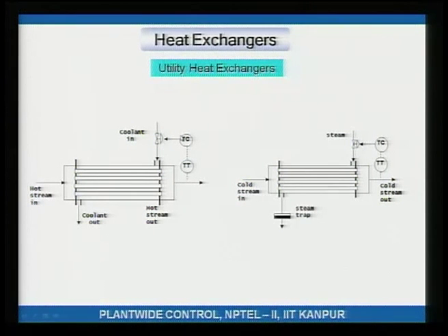Okay. Alternatively, you have a cold stream going in and you are putting in steam, and the steam is heating this cold stream to a certain temperature. Well, if you want the temperature to be at set point, let us say if the temperature is more than what it should be, then you will pinch this steam valve, right. So, these are essentially very straightforward things that you do. Essentially what you are doing is adjusting the heat transfer, or the heat removed or added, to get the desired temperature of the process stream. You are interested in the process stream having a desired temperature.